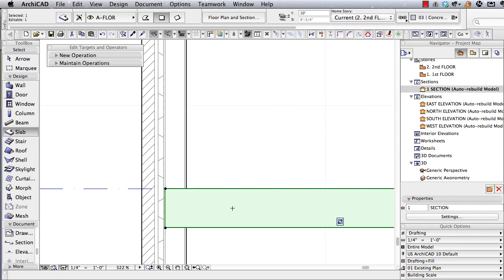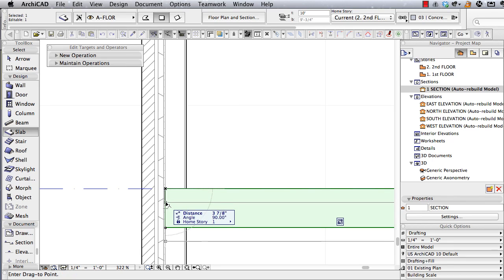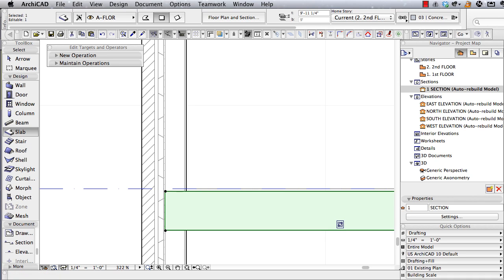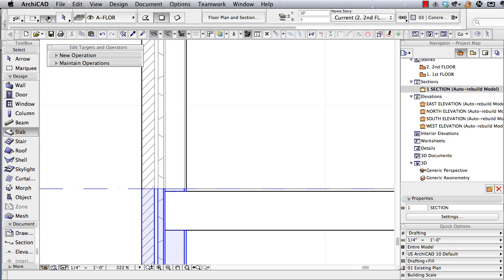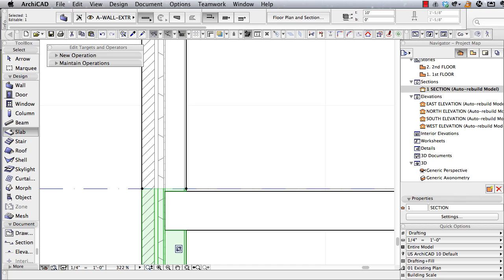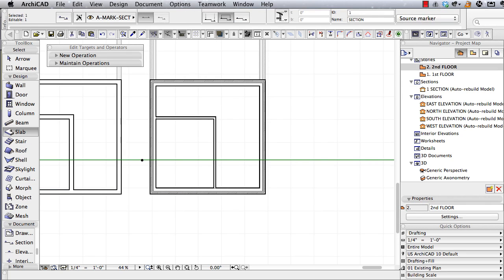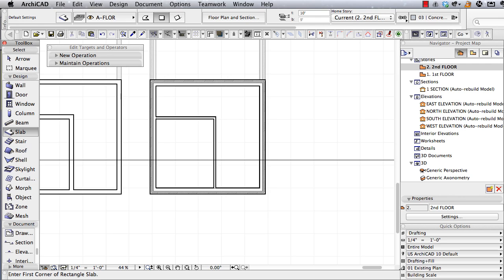And you can see how it's simplified, and it's gotten a little tiny bit thinner because it removed that structural component. Now, it kept the top surface, and actually I wanted it to keep the bottom to allow space for the finished floor. So I'm just going to drag it here, just using Command D or Control D, the 3/4 of an inch, that's about 2 centimeters down, and you can see how it's changed the top height as appropriate. So it is now in the right place. This upper wall here, you can see, is sitting on top of the story level, and this lower wall actually is wrapping around here.